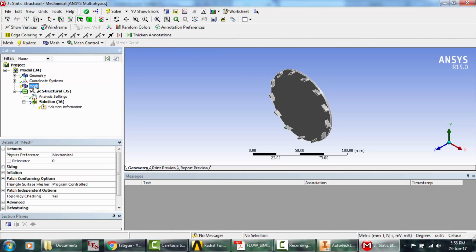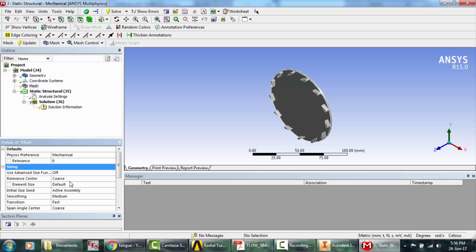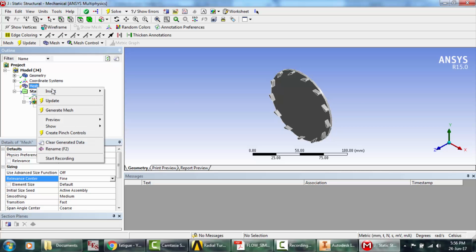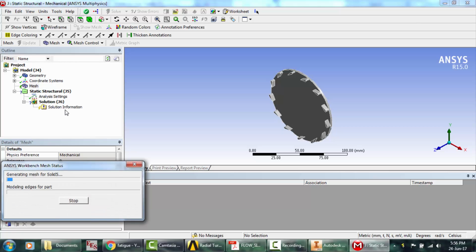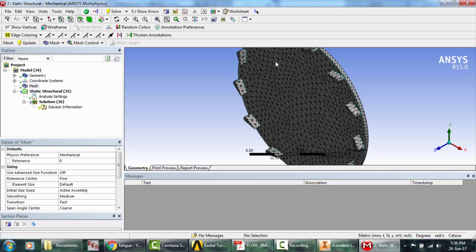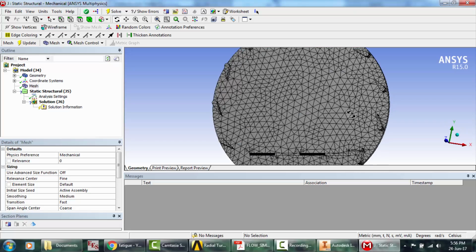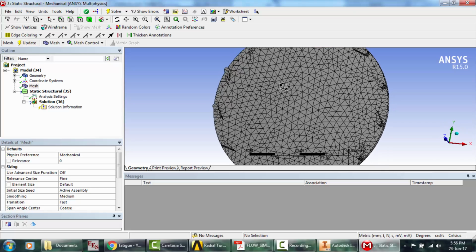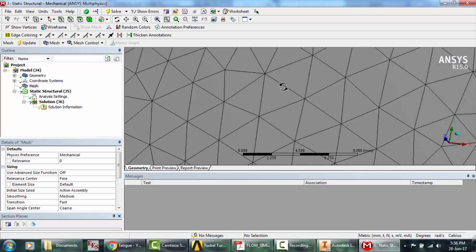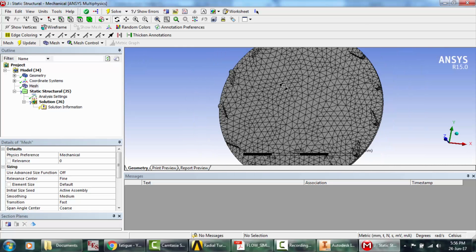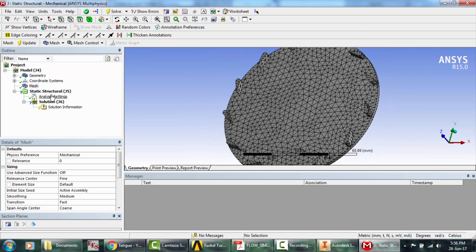Okay, here is the mesh sizing. Also, you have to check the Y plus and the appropriate size. Please do not follow my size. And here we go, so this is the mesh. It's a coarse mesh, still coarse, but it may work.